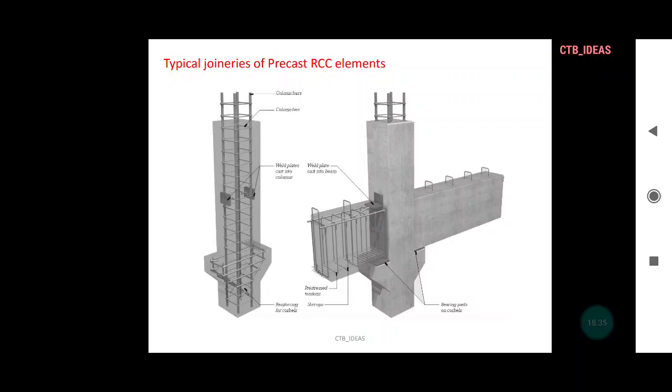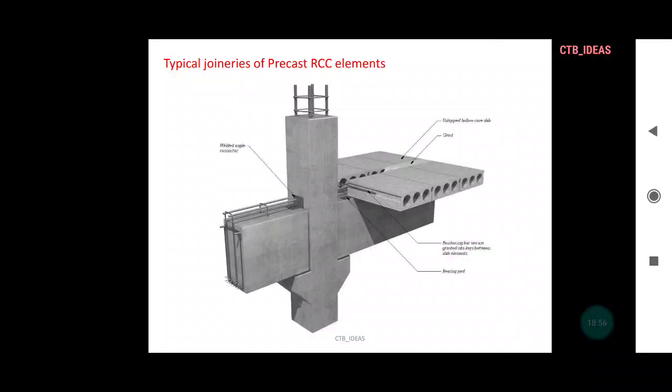One leg of that particular angle is going to be welded on the vertical part of the column, and the horizontal part is going to be welded on the top part of the beam. In this way, the joint between column and beam is secured. This is clearly visible in this particular image. If you go through the finished horizontal beam resting on corbel, the angle section you are seeing in this image is the welded angle section. It is also called an angle connector. So this is secured in this way.